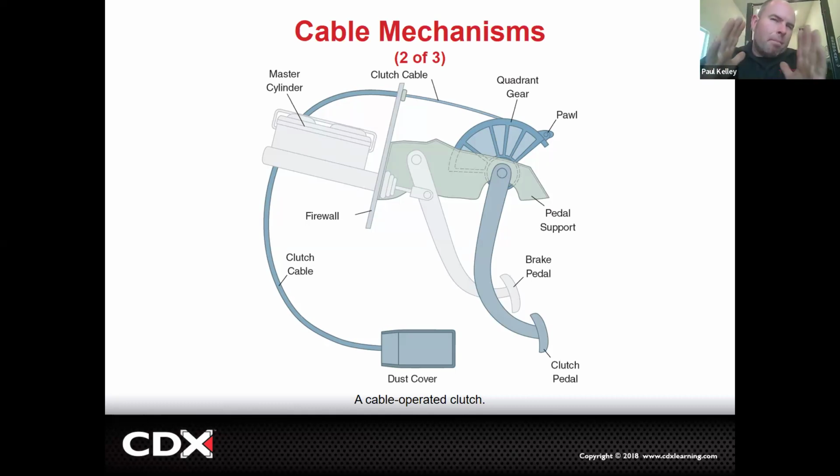So it's like, hey, clamp, but don't clamp all the way. Like, let me release you just a little. What's going to happen at wide open throttle? Come on, give it to me. Anybody know? No, you do. Wide open throttle. Clutch is partially disengaging because the cable's too tight.